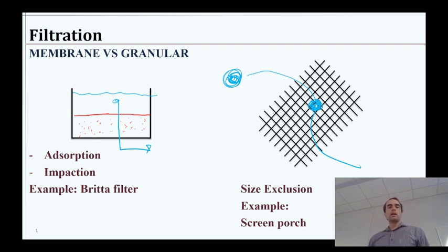So instead, what we're looking for is actually a combination of different little processes, things like adsorption, or maybe the particles, as they're flowing through the little channels, literally sediment or perhaps impact onto the sand grains, okay? Or whatever granular media we're using. So it's kind of a collection of physical processes. They stick to the surfaces. Maybe they start sticking together, as we'll see in a second. And any of the particle destabilization we achieved with the coagulation, that's going to help in this part too.